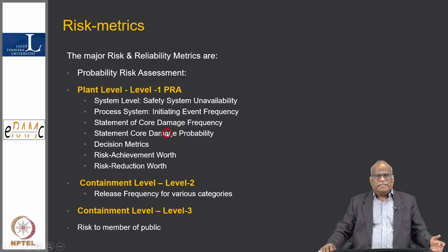And the core damage probability, of course, if I have some certain issues to be prioritized, identified now, then I use core damage probability. It is more of academic interest, but with core damage frequency, I can compare two similar plants: what the system performance is, what the initiating event frequencies are. So it provides a very integrated and holistic metric which enables our selection.